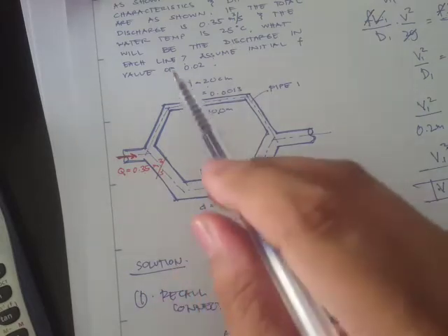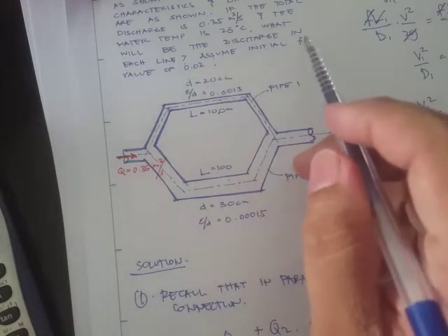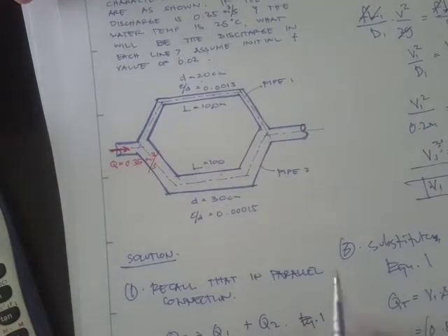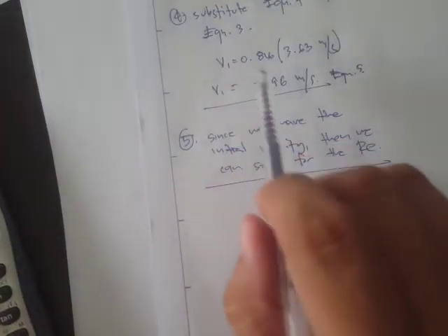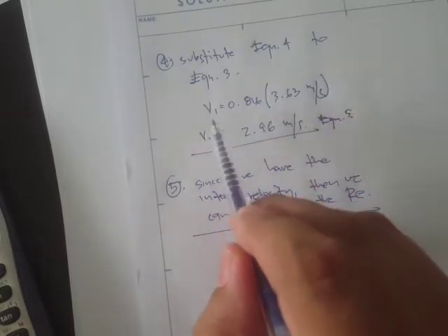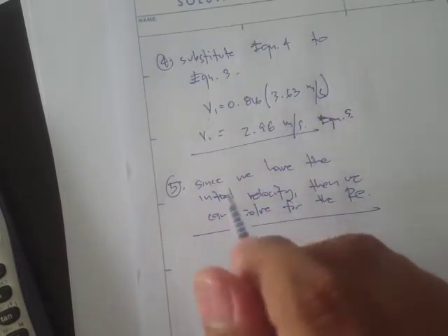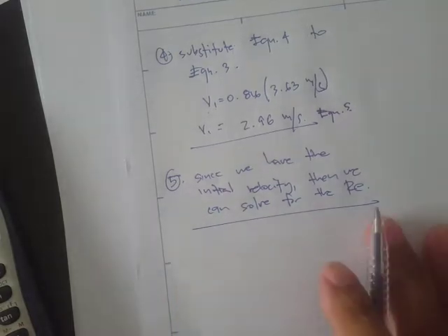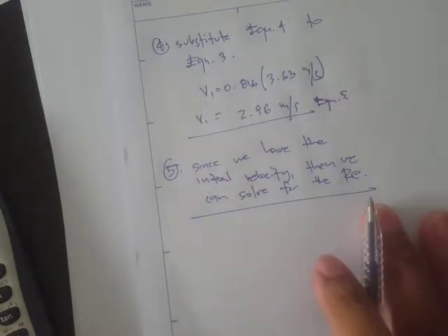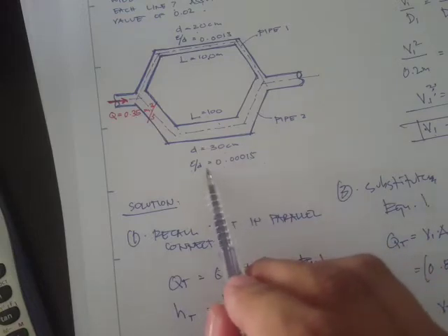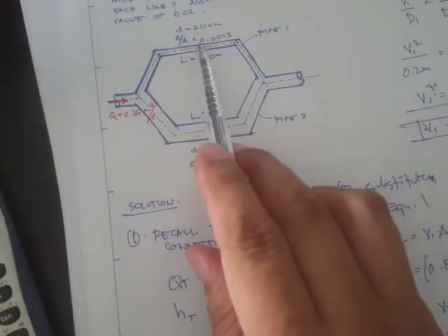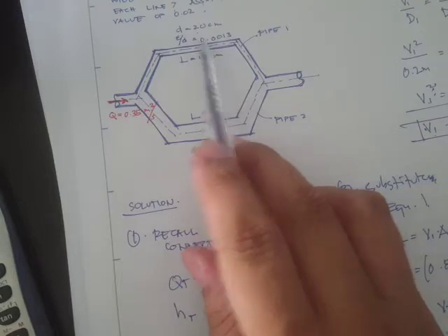So we have to guess actually the friction factor, and then iterate if necessary. This velocity is obtained from an initial friction factor, but we have to check now. We know that the friction factor would be different because we have a relative roughness that's different.